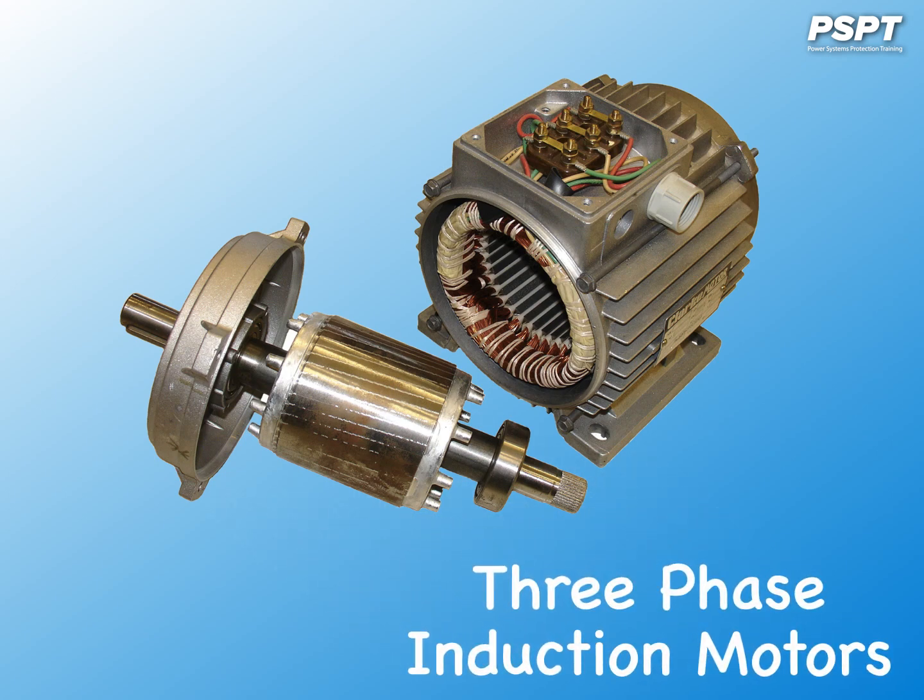Three-phase induction motors are the most widely used electric motors in industry. They run at essentially constant speed from no load to full load. However, the speed is frequency dependent, and consequently these motors are not easily adapted to speed control. We usually prefer DC motors when large speed variations are required.